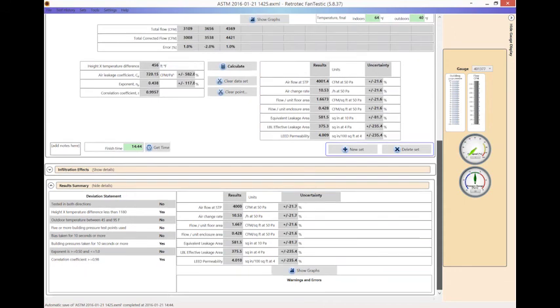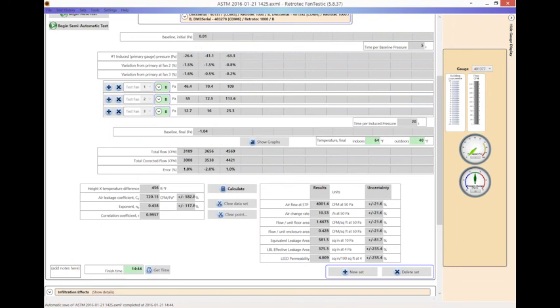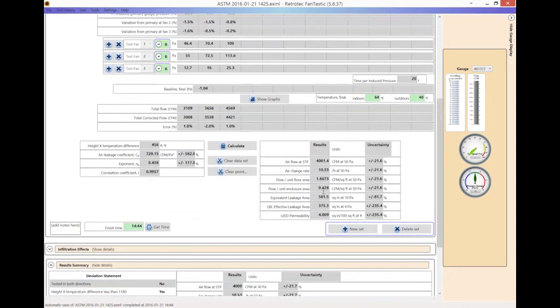So let's scroll back up, and I can show you that over here my results are based upon the information we put in the building. Remember our square footage and enclosure. I can see my air change rate is 10.53, so definitely not a well sealed structure that we have here. And you may be looking for flow per enclosure at CFM per square foot. 0.4 is kind of the higher range of that. And this is, again, leakage per surface area of the structure. And just above that, I have my air change rate of 10.53.